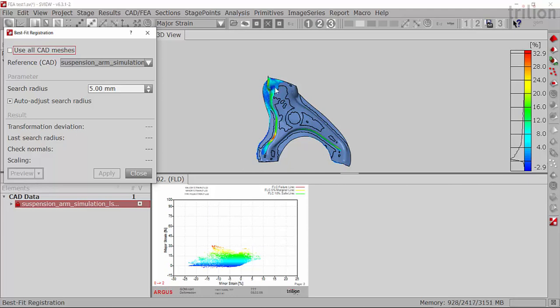I wouldn't only pick the end of the part for the same reason. It might skew the middle of the part that might be sitting well. Conversely, if you're looking at a part that's oil canning quite severely while it's sitting on the table, just have the acknowledgement that you have full control over picking areas that will lock this part in and be able to compare it nicely across the way.